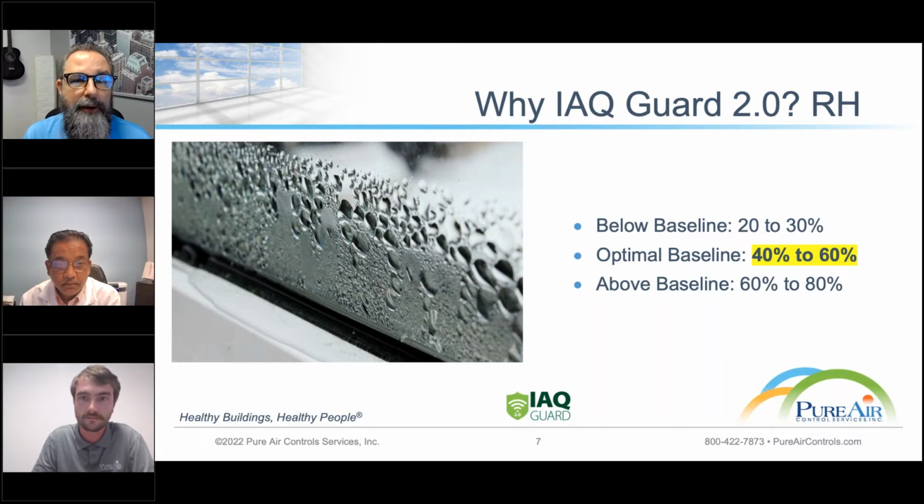And we've had customers where they've had duct cleaning performed by a substandard company, and they blew all of this debris into these reheat coils, and now the airflow is obstructed, and the humidity within the occupiable spaces dramatically rose and very quickly rose and stayed at a very high level, and it caused all kinds of mold issues in